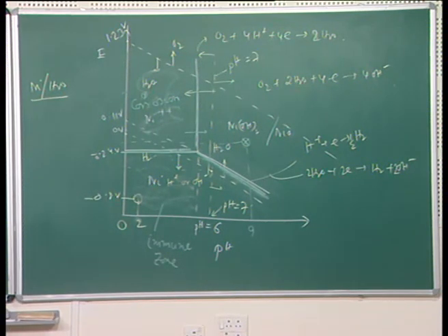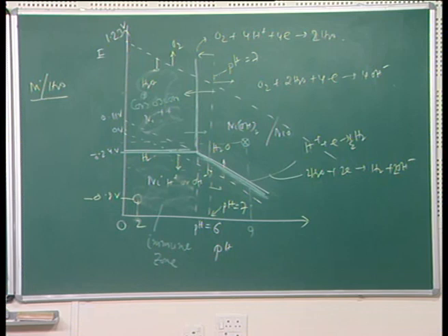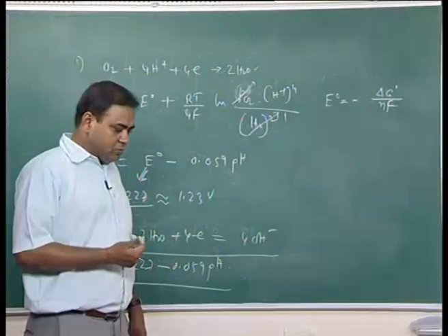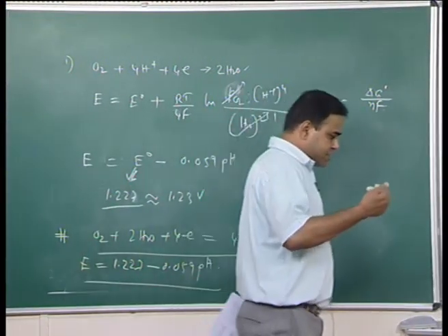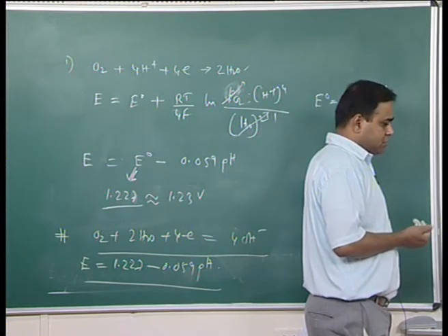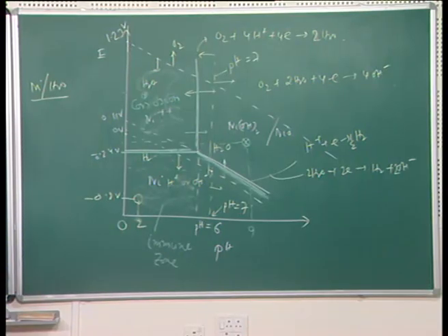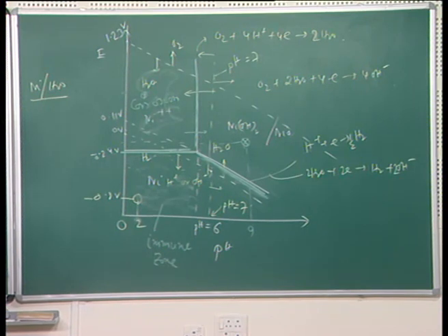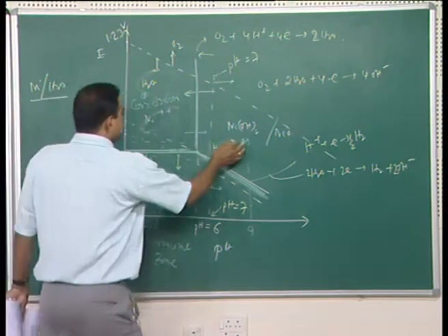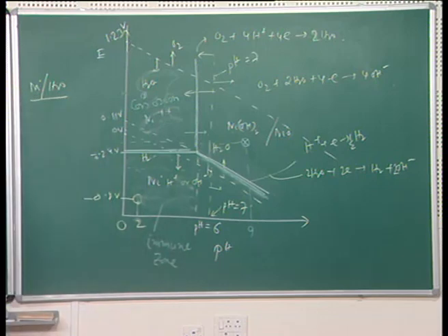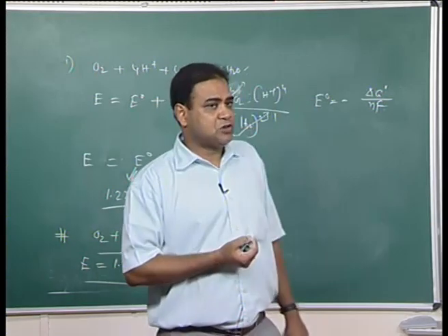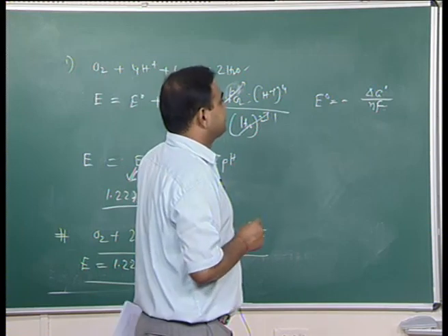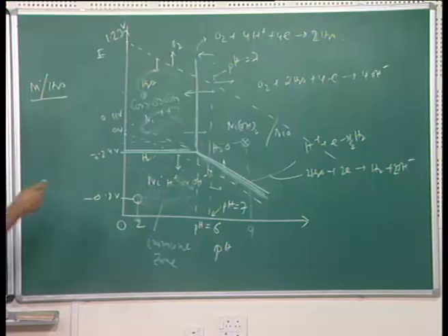Now, Ni(OH)2, we have seen one problem, that at certain pH value of the solution in deaerated H2O medium and with the solubility product of Ni(OH)2 at 25 degrees Celsius, we see that the nickel corrosion is not spontaneously possible. We have seen from thermodynamics. Now, this Ni(OH)2 forms a layer on the Ni surface which prevents nickel dissolution.